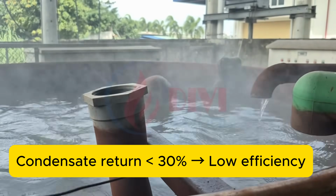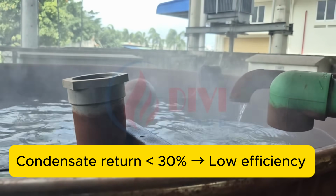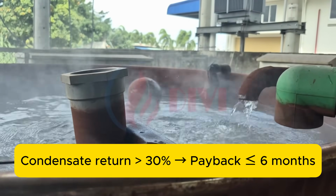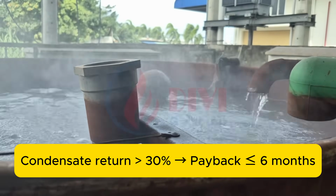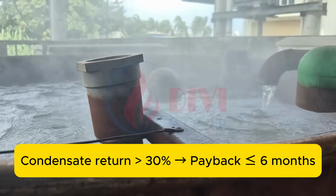However, if the condensate return rate is below 30%, the benefits may not be significant. If it exceeds 30%, the payback period is typically less than 6 months for continuously operating systems. If your factory is recovering condensate but not aware of flashing losses, it's worth checking. You could be losing money every hour without realizing it.